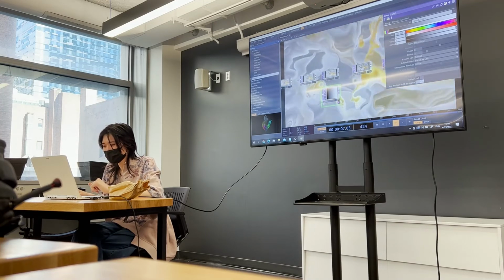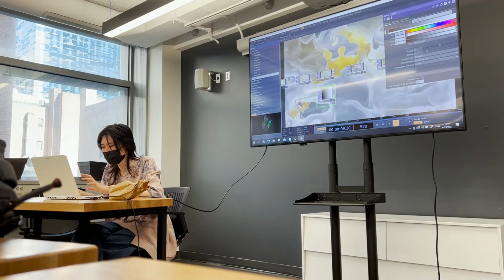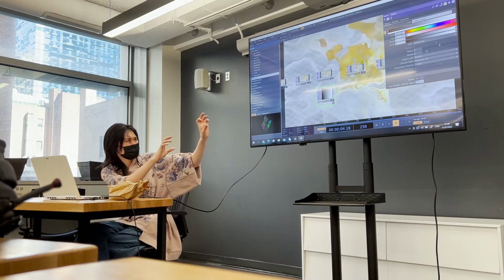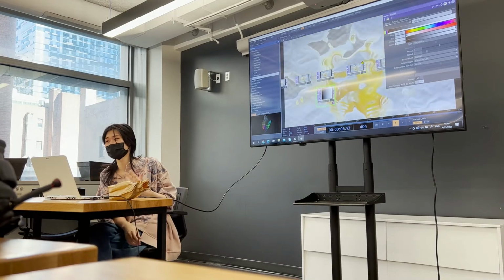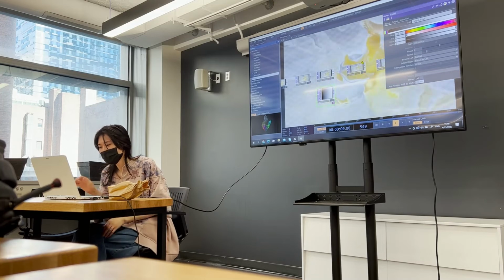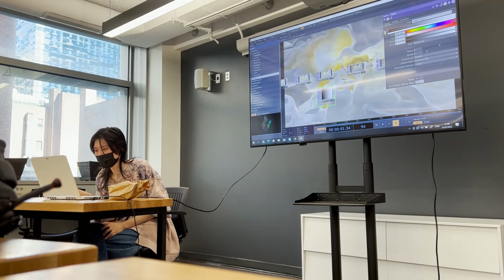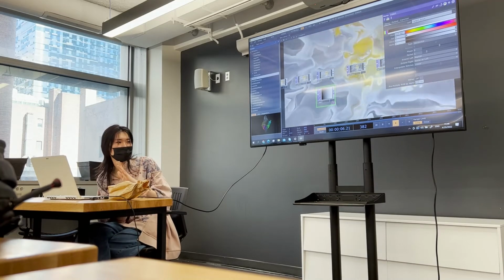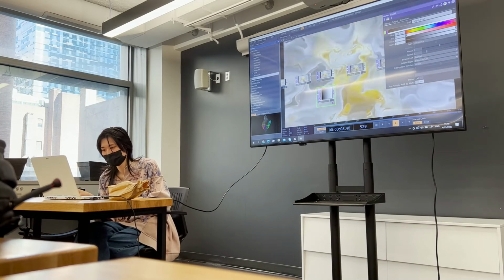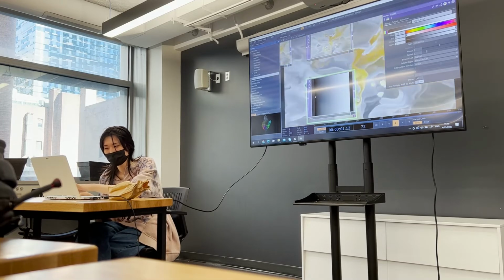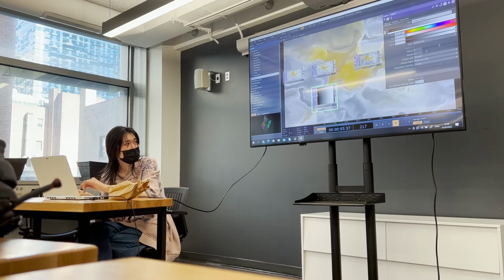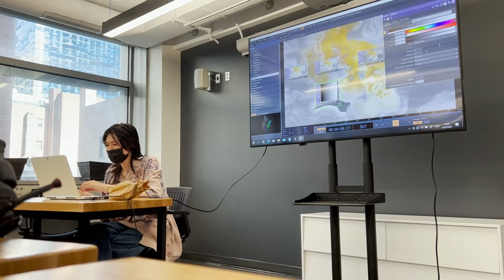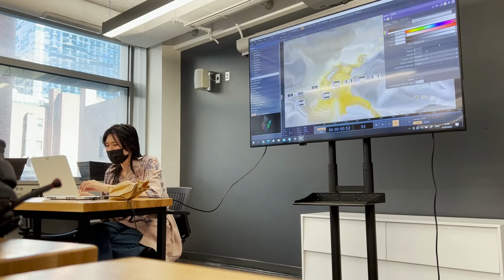essentially it's going to change, so you can see before this, let me disconnect it. You can see there's this check pattern, which means alpha value equal to 0. And if I put it back in, it's going to be black. Because when there's no alpha value, there's also no luminosity, it's going to look it up at the rightmost side of this ramp, which is black. So now we have this ramp, or it's looking up the texture.